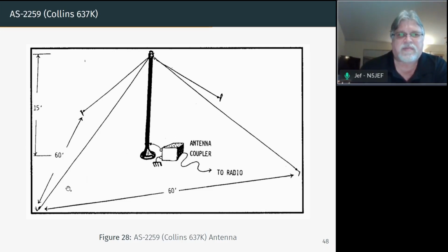So these elements coming off 90 degrees from each other don't have to be resonant, is the point. So the military can set this thing up very quickly. Doesn't have to be resonant. It'll work on a wide range of NVIS frequencies, and you can tune it here with low loss on the center mast.